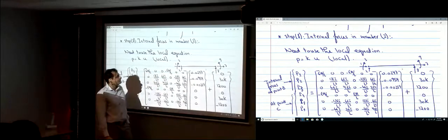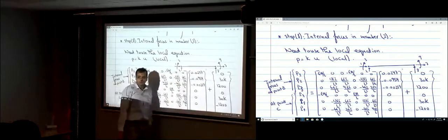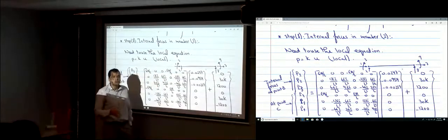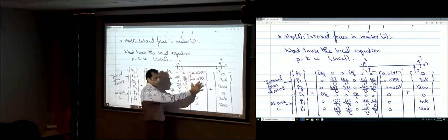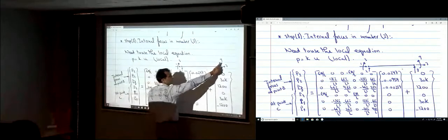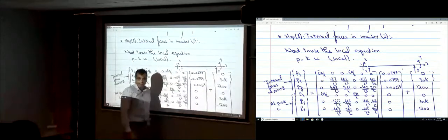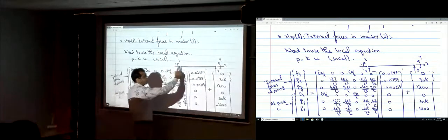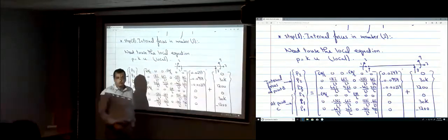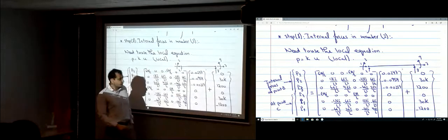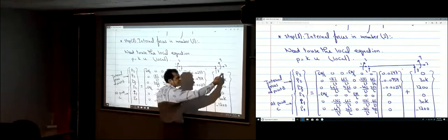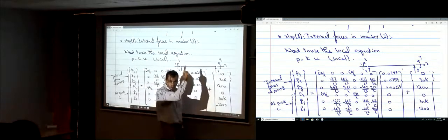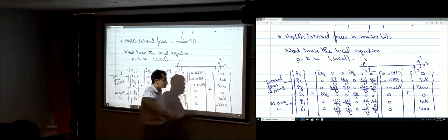And fortunately, this member is oriented with the X axis, so the local direction is the global direction for this member. So the displacement that we found in the first step is the same in the local direction. I don't have to transform them. And the displacements over here are zeros, plus the effect of the intermediate loading. I put the effect of the intermediate loading not as an action, but as the reaction, so I'm putting it in the opposite direction to what we found initially. Those are the actions there.